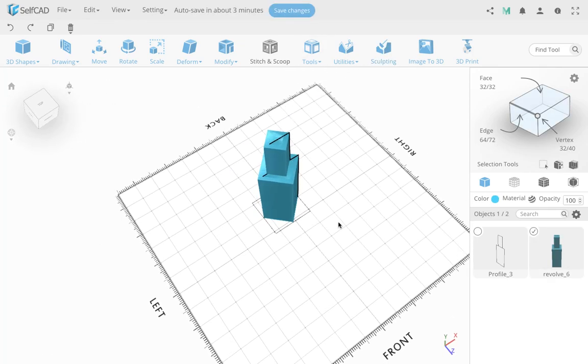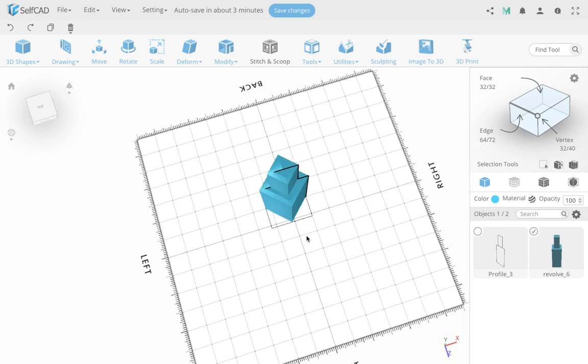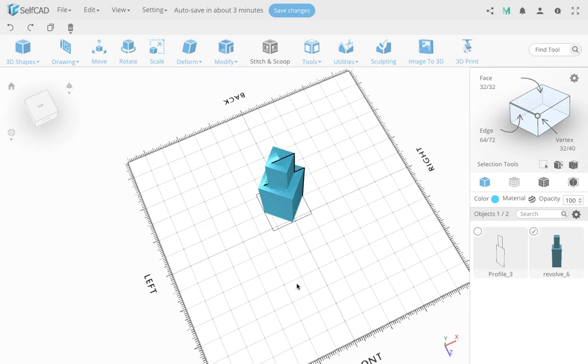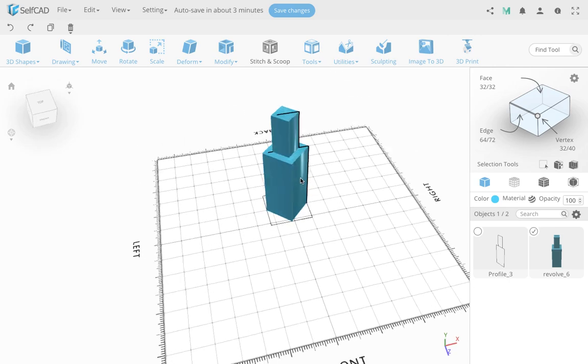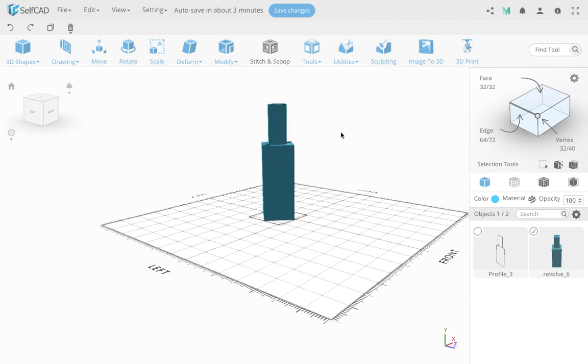Now I got what I was looking to get, but this shape is not 3D printable yet, because it's self-intersecting. It's difficult. I can play around to get the exact position to make it collapse exactly the inside without self-intersecting. Self-intersecting basically means that one side goes into the other side, and they all kind of mingle together, and that becomes non-printable. If it's not self-intersecting, I still have my basic size over here.